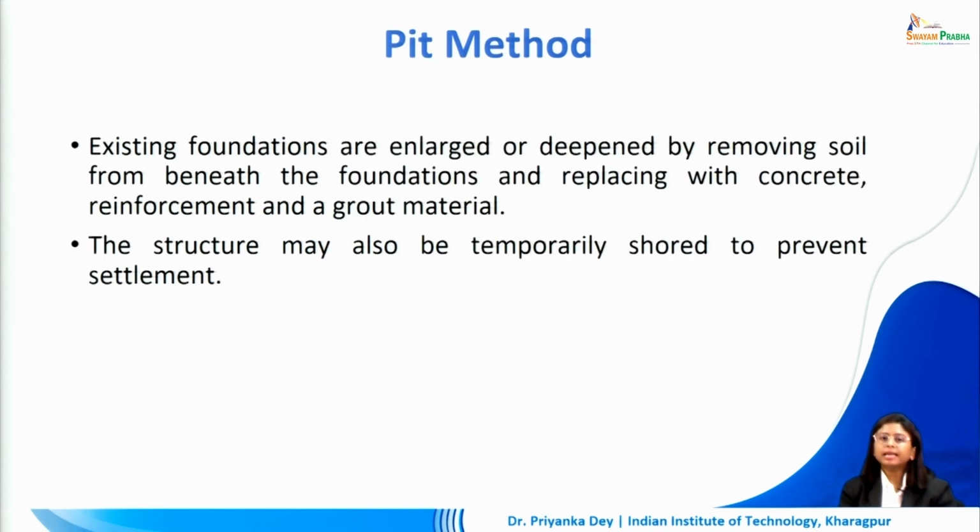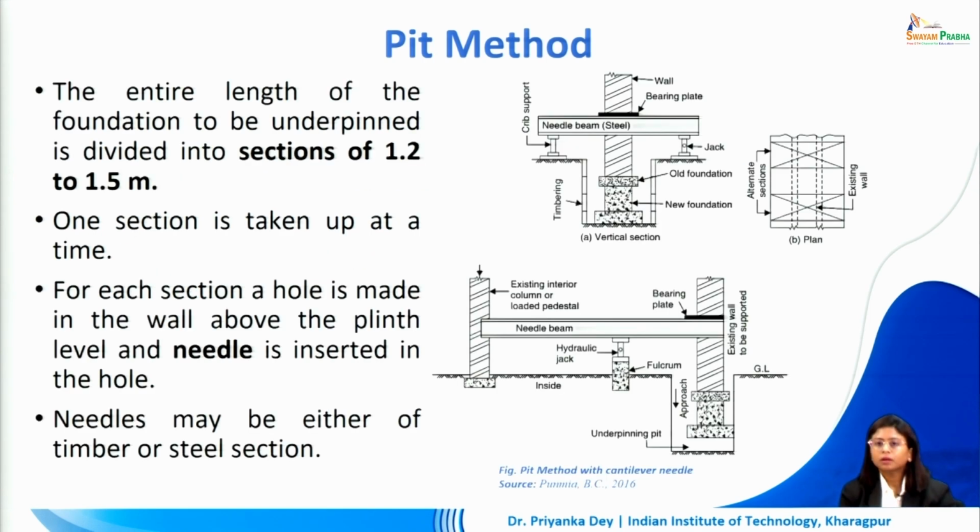Now here the existing foundations are enlarged or deepened by removing soil from beneath the foundations and replacing it with concrete reinforcement and a ground material. The structure may also be temporarily shored to prevent settlement. So raking shores can be used to support this structure. So how do we go about the pit method?